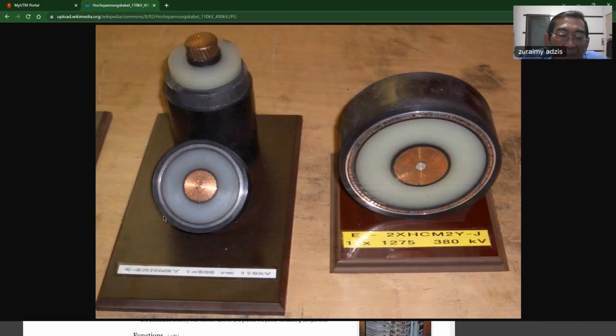In terms of electrical property, these outside layers are semiconductive. Why should it be semiconductive? Because if it is not semiconductive, charges will start to occupy the surface. And when you have charges occupying the surface, you are talking about build up of voltages on the outside of the circumference of the cable.